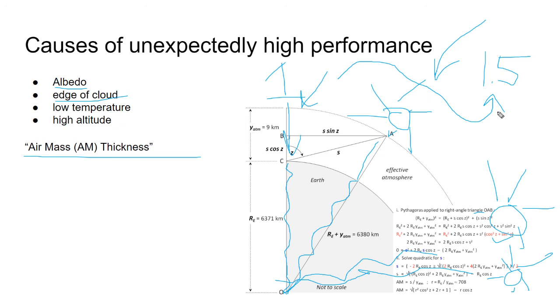And so I guess the quiz question over air mass thickness would be, if the sun is up at 10:30 at a 77-degree rooftop temperature with 1,000 watts per meter squared in the sunlight versus high noon at the same rooftop temperature at the same amount of sunlight, which produces more? And the answer is high noon because there's less air mass.